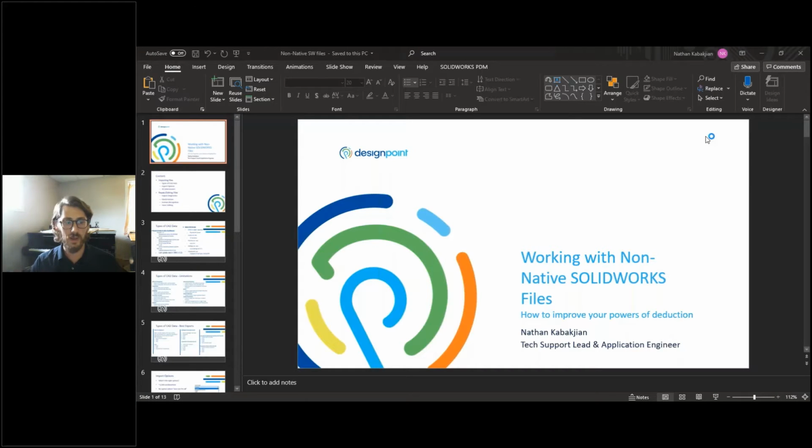One, if you are a SolidWorks user yourself and you know you've got to send a model to another SolidWorks user or some other vendor, it's relevant to try to export your models as something that you might more easily import later, especially if they are also using SolidWorks and you don't want to send them a SolidWorks file with a feature tree fully accessible. These are things that are worth considering.